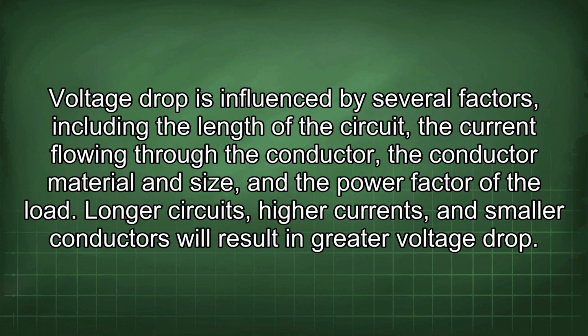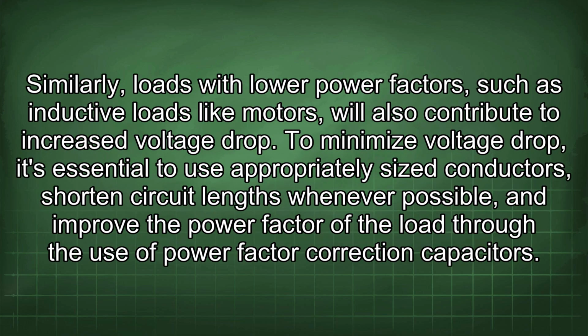Voltage drop is influenced by several factors, including the length of the circuit, the current flowing through the conductor, the conductor material and size, and the power factor of the load. Longer circuits, higher currents, and smaller conductors will result in greater voltage drop. Similarly, loads with lower power factors, such as inductive loads like motors, will also contribute to increased voltage drop.